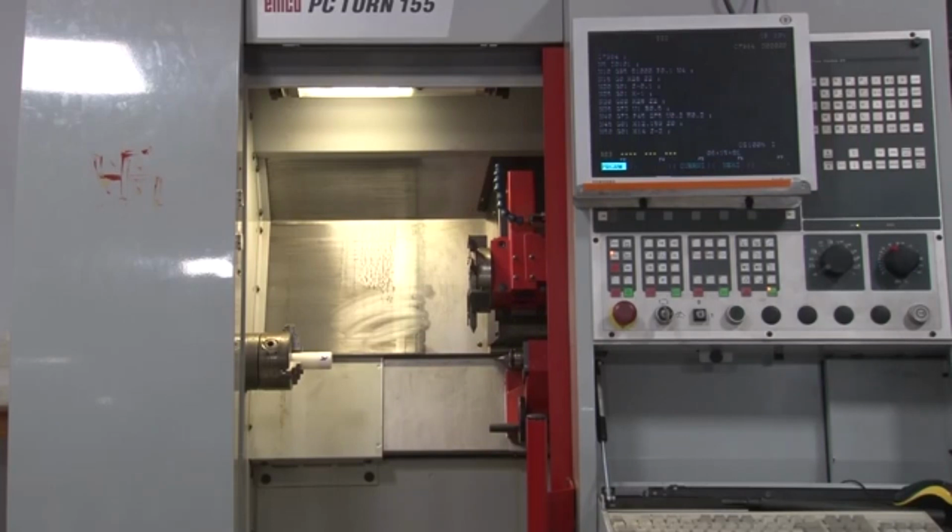For that, the first step is that we have to call the appropriate tool which is required, in this case tool number 1, and that tool has to come to the 0 position. It will touch the exact 0 position of the tool which you have determined, and for that we will be using the jog mode. As I told you already, the jog mode is when the tool has to move slowly. We will not put it very rapidly, to prevent any kind of accident in case it may happen. So, we will put it in the jog mode, and tool number 1 will be called and brought to the 0 position on the workpiece.